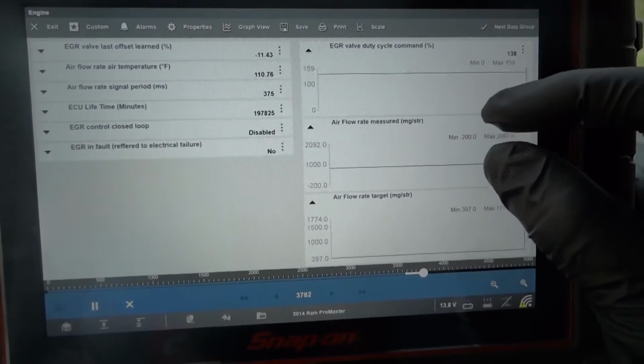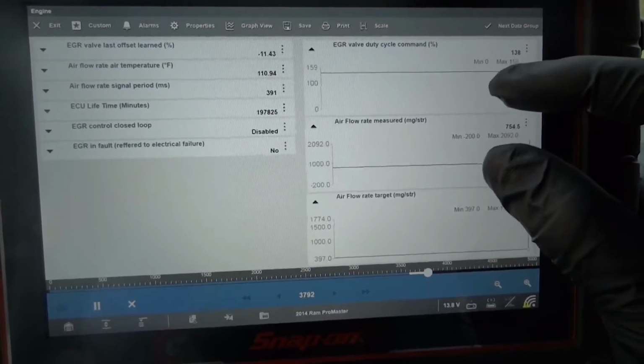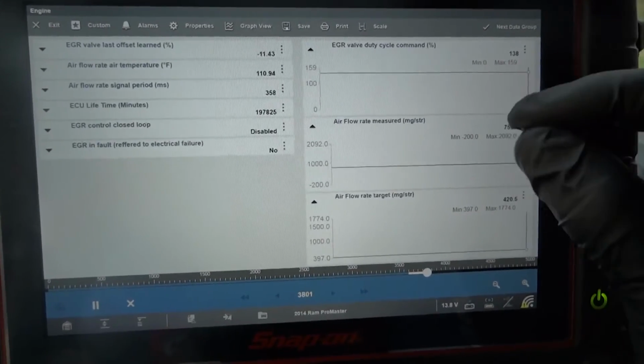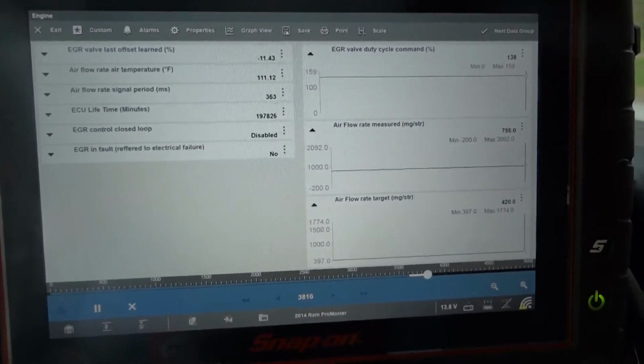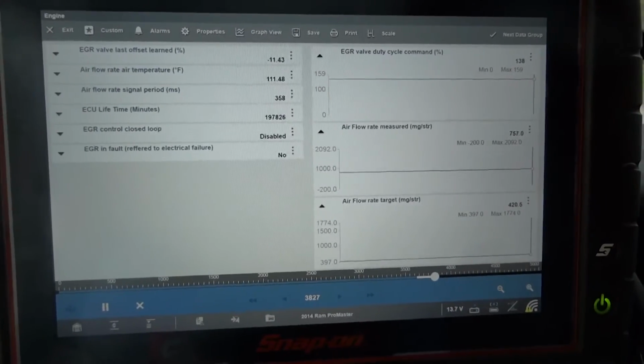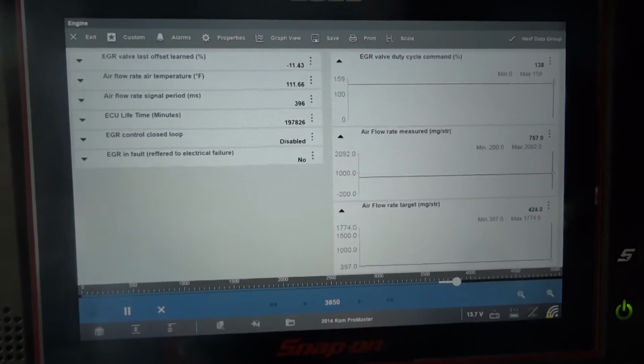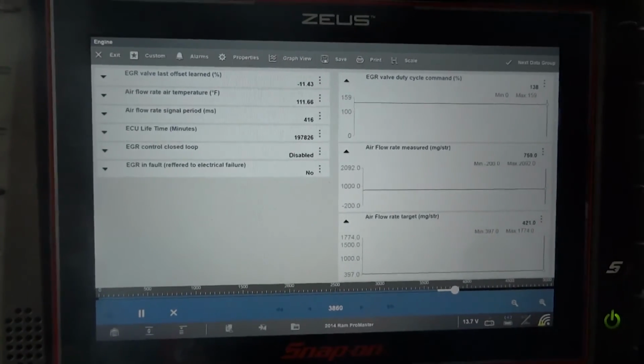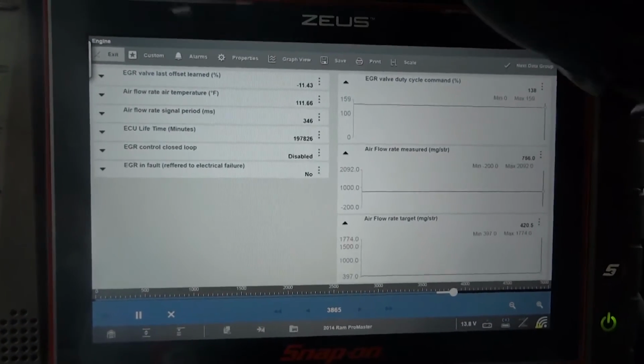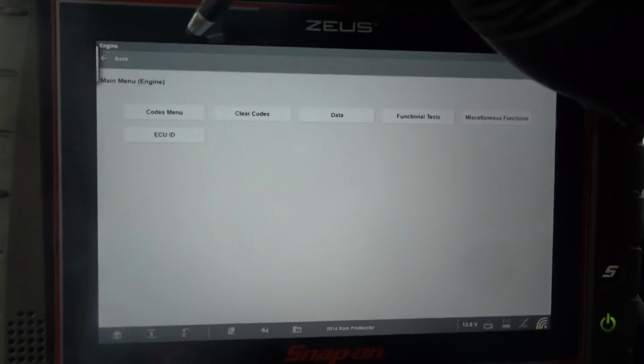If you have a valve opened halfway, it's going to send exhaust gases into the intake. And when an EGR valve opens at the wrong time, if your EGR valve opens at idle, it's going to cause the engine to not even run. The idle is going to be sluggish, and the engine is going to die. One thing we can do is, let's back out. Let's read the code. Let's see which code came back.